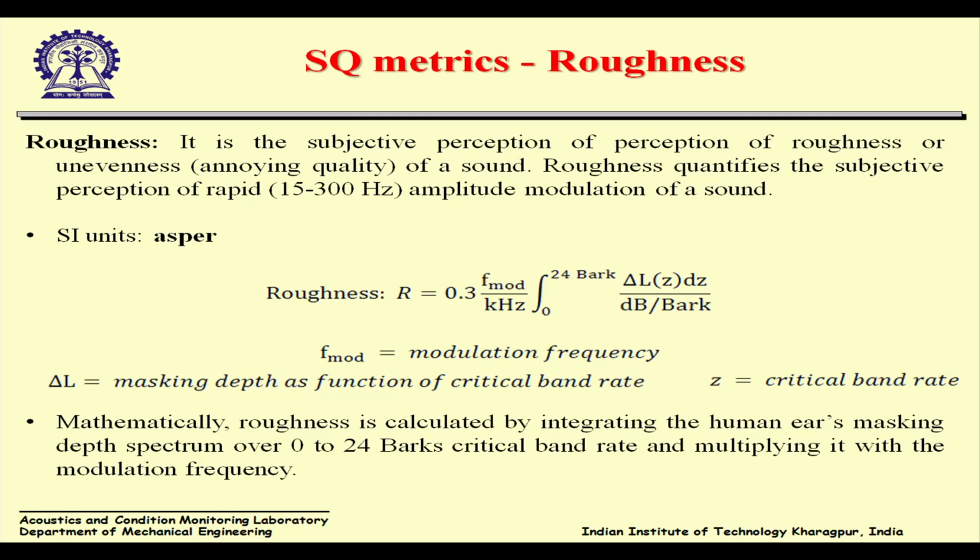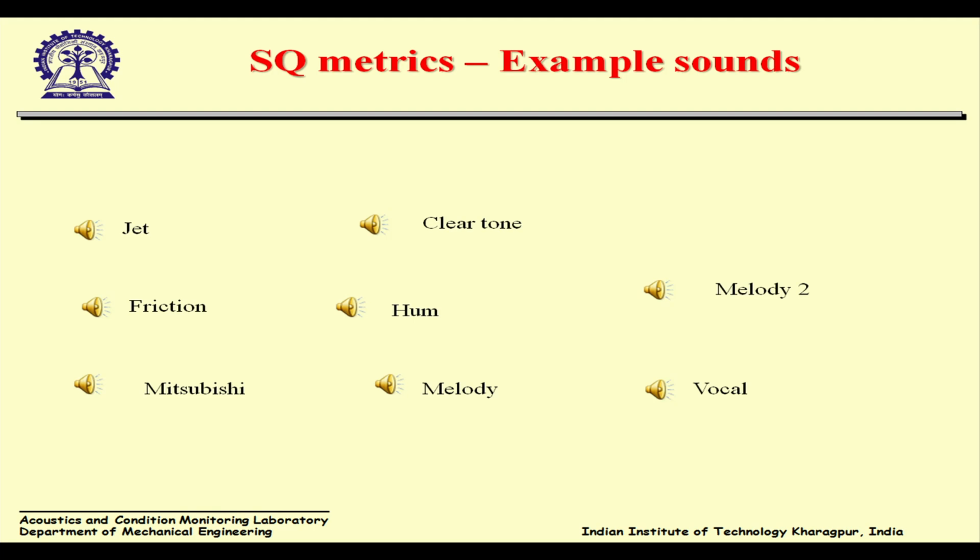For example, loudness correlates to the loudness, fluctuation to how fluctuated the sound is, and roughness to how rough or annoying a sound is, and how it's calculated from the sound signal. So first it's converted into critical bands and then a specific loudness curve, and then various processing is done. So how these metrics are calculated, and then once calculated, how they are used for improving the sound quality. So these are the 4 metrics that I have discussed. I'll skip this because this is a part of our lab.